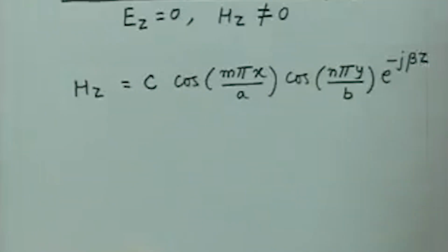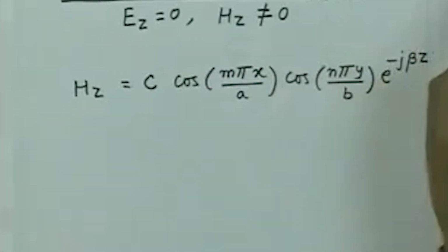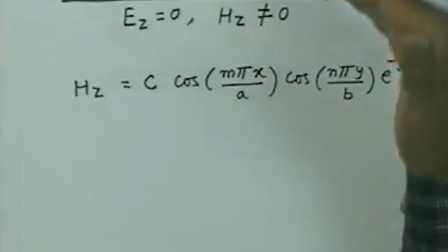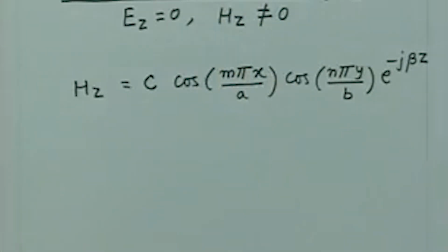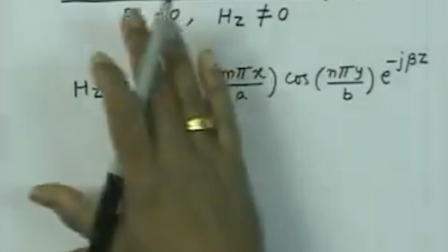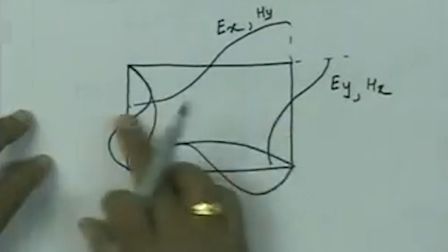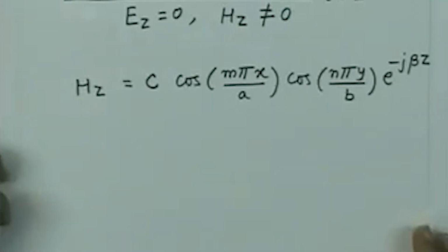So in this case, TE case, if I go by the routine way, there will be two steps involved. First find out the general solution for Hz, substitute into the transverse component expressions, find transverse components, and then apply the boundary conditions on the transverse components, because intrinsically there is no boundary condition on Hz. However, without going through the same routine steps, essentially the understanding which we develop that the magnetic field when it becomes tangential to the conductor is maximum, I can get the expression for Hz, and one can go and verify that if I had done the rigorous analysis, essentially I would get the same expression.